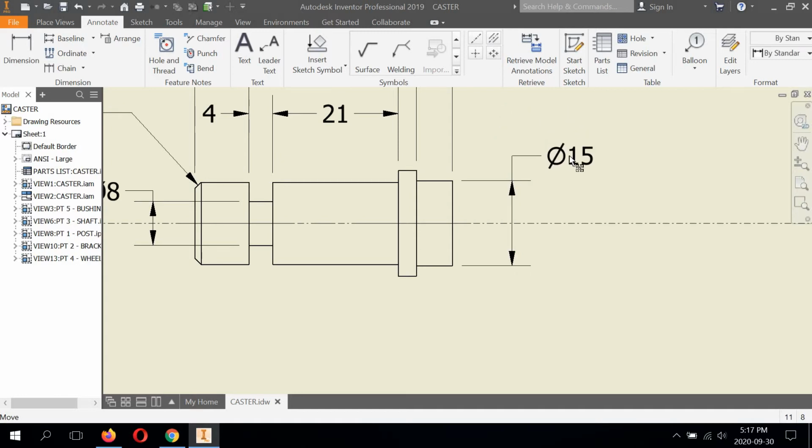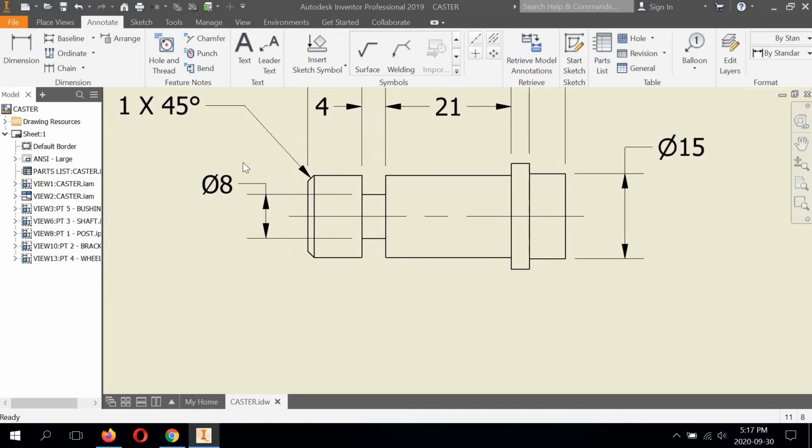We're going to just turn this like this. And I didn't have the luxury of doing that for this groove diameter because I couldn't select just that line by itself. It forces me to select this one, and I don't want it. So I had to manually insert a diameter symbol here. Anyway,